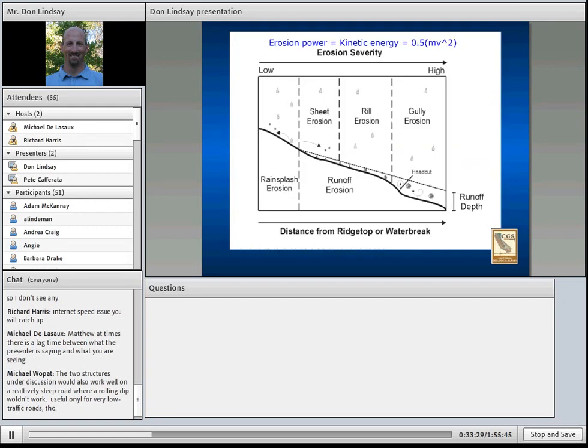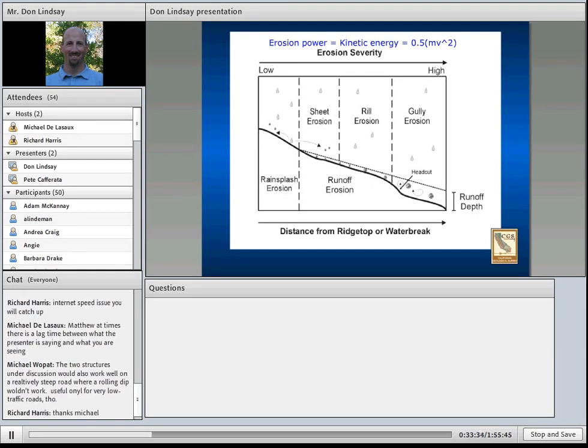To recap somewhat what Drew shared in his presentation in Series 1, the erosive power of moving water is a function of the mass of the moving water and its velocity. The more moving water there is and the faster it flows, the more erosive power there is to create rills and scour gullies. So the main idea is that we want to space drainage structures close enough to shed the water off the road, thereby reducing the water volume before it has a chance to form rills and gullies. By doing so, the road will become naturally more hydraulically invisible.